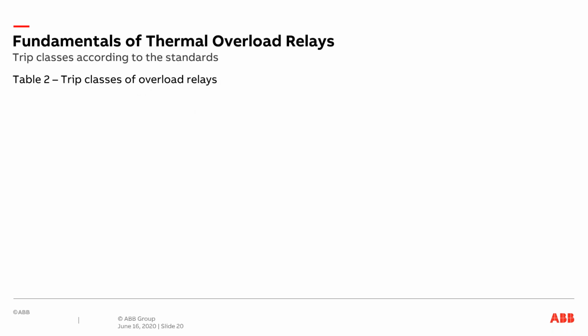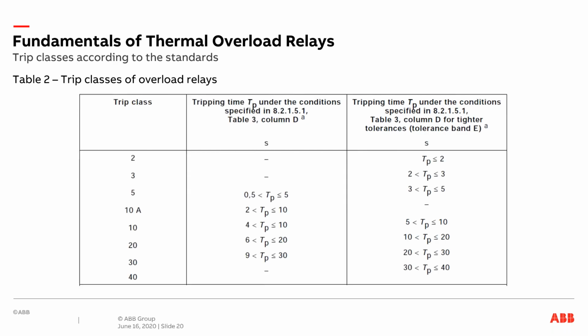So now I will talk about thermal overload relays. We always come across thermal overload relays and trip classes. This is something very important when you have an overload and you need to set the overload depending on the application. You need to take into consideration the tripping time as well, because every application might have a different kind of start. It can have a long start, and the motor can take time to actually go to its full speed. So depending on that, you need to select the right class.